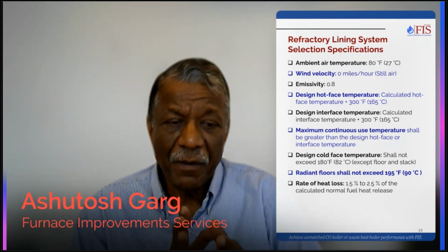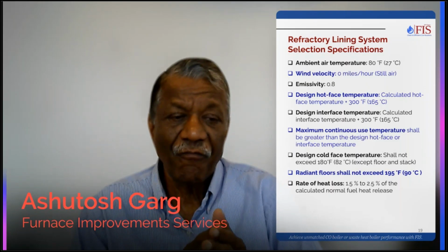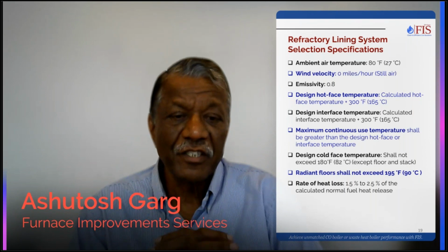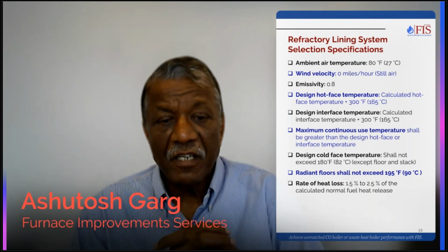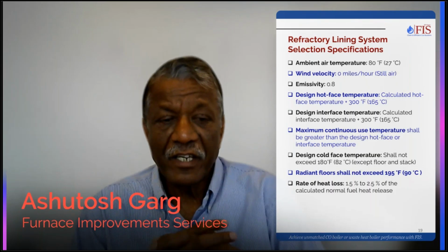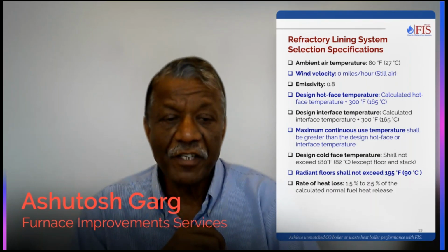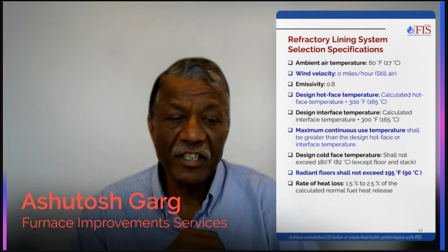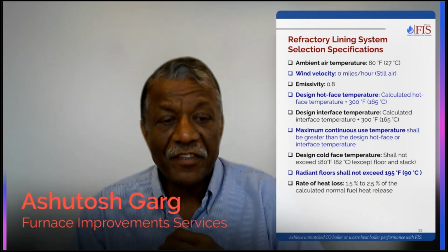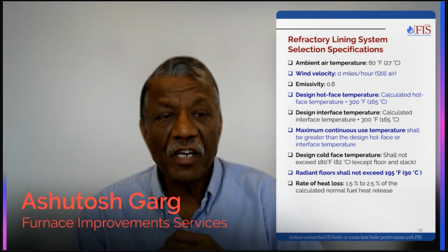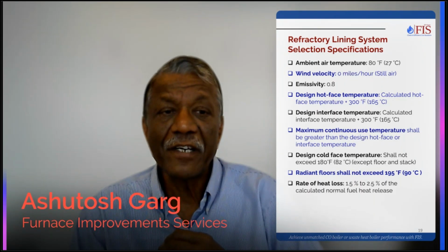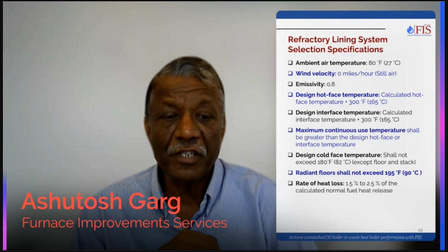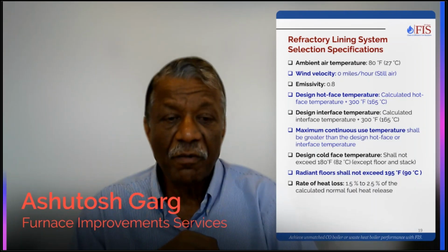Floor we permit to go up to 195, and stack normally we don't care actually, because nobody is going to touch the stack. But one thing which is very important is you want to make sure that your heat losses are no more than 1.5 to 2.5 percent of the total heat release. And this can be a misnomer if you are in Europe, because of the low ambient temperatures, your heat loss could be much higher, even though your casing temperature is 180, your heat loss could be much, much higher.